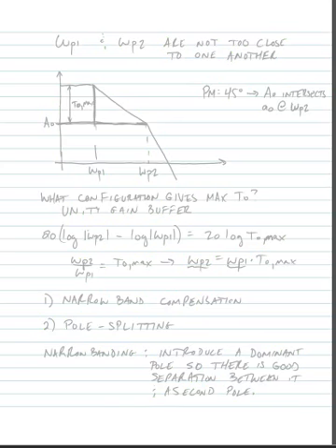So let's begin looking at the compensation of op amps. What we in general want to do is make sure that omega P1, our first pole, and omega P2, our second pole, are not too close to one another in frequency.